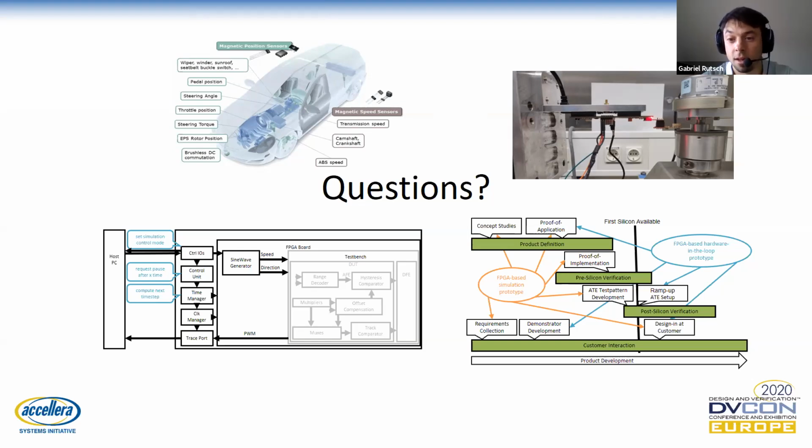So I mean, cost is a very significant differentiator. On the other hand, especially if you want to trace more signals or you have to trace for a longer duration of time, this is really where an emulator shines. This is why they have this additional instrumentation around the Xilinx chips in order to allow that. And they have a quite convenient software stack to enable tracing entire systems for a long period of time. However, one of the things that you cannot do that easily with an emulator is really have a hardware in the loop setup. This is one of the reasons why we targeted rather the smaller FPGAs.